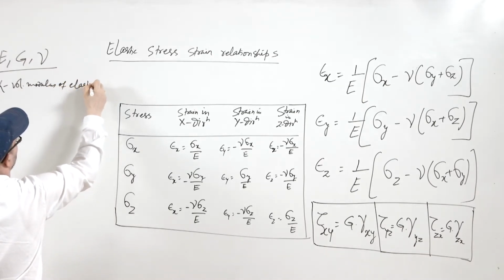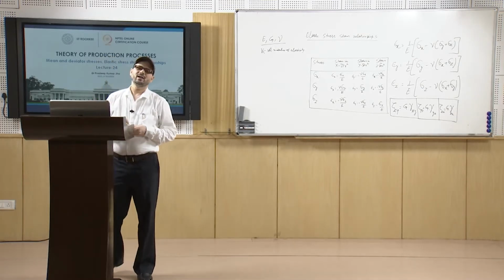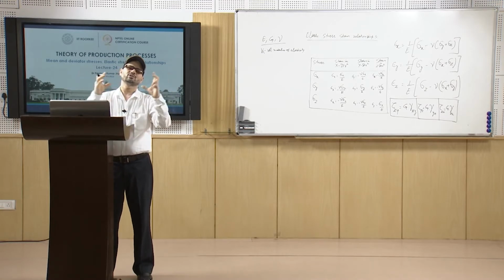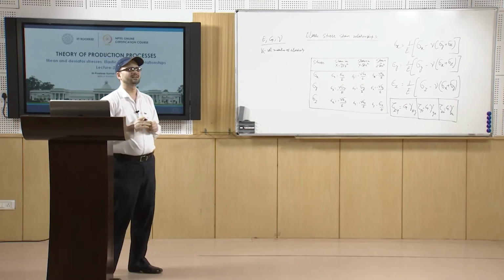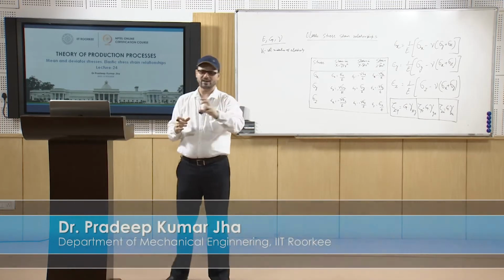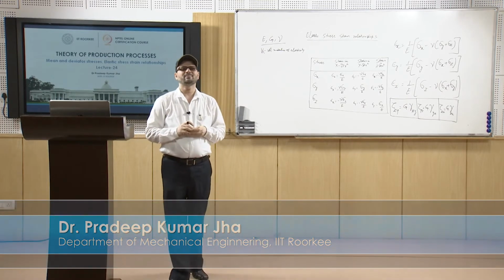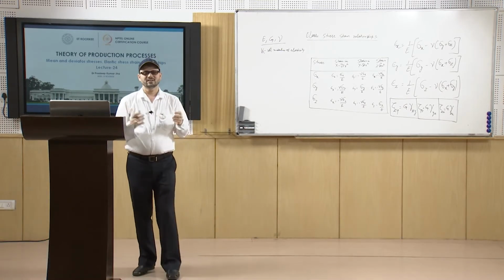Now, in this case again you have the stress by strain, and the stress is your mean stress. So, that is minus P if P is the pressure which is equal at all the places. So, it will be minus P divided by volumetric strain, that is delta.